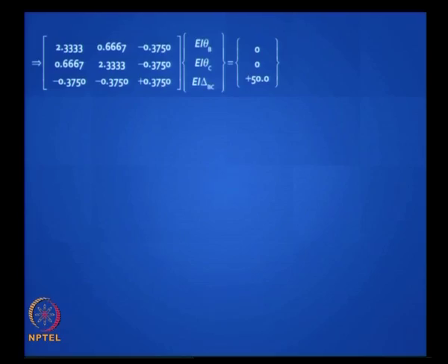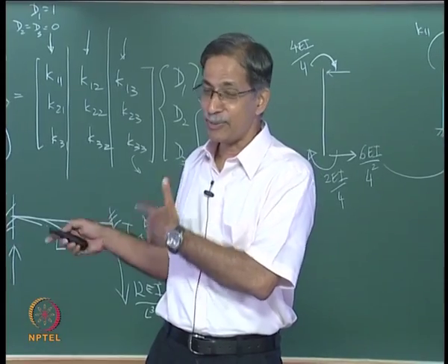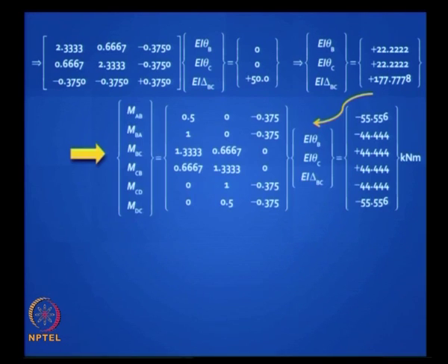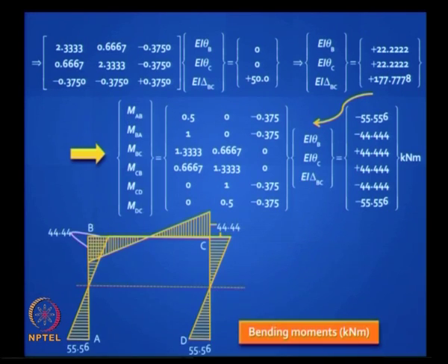So now you see this is the stiffness method which we are going to do soon. Solve it, plug it back into the slope deflection equations, you get this answer which we got. Now look at this problem. I am going to raise a question and we will stop this class. There is something nice about this bending moment diagram. What do you call such a figure? It is not symmetric, it is anti-symmetric.